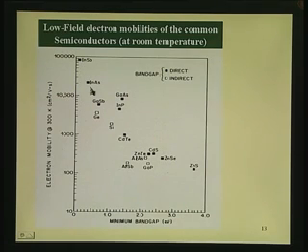So, you do not go and jump into that and say, I will take this indium antimonide and make use of it for making my high speed devices. Your high speed devices with that material, if it has to work, what should you do? You must cool down drastically, because at room temperature itself you will have plenty of electrons, and junction will not work like a junction.